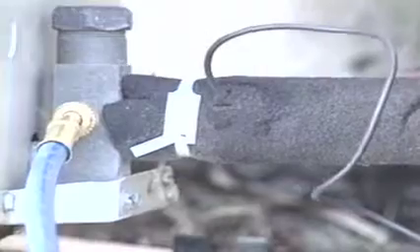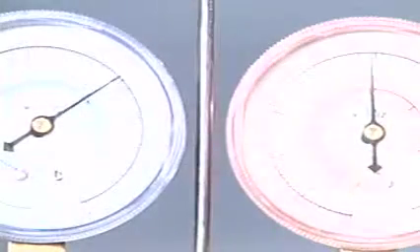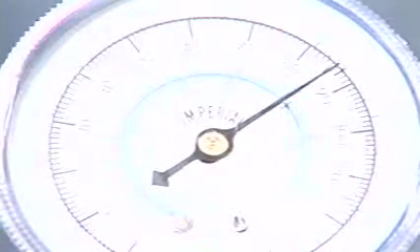To determine the amount of superheat, use this formula. The suction line temperature minus the saturation temperature equals the amount of superheat. To get the suction line temperature, attach an insulated temperature probe to the suction line. Then, to calculate the saturation temperature of the low side, read the low side operating pressure and convert it to temperature using your temperature pressure chart.